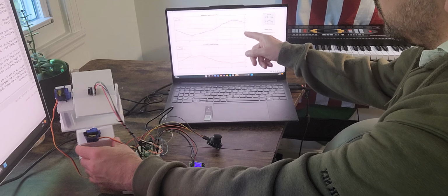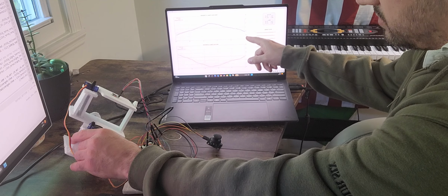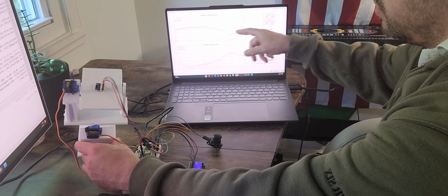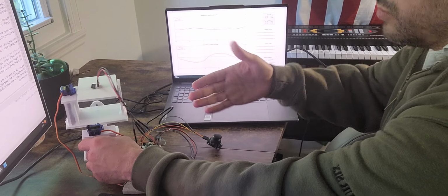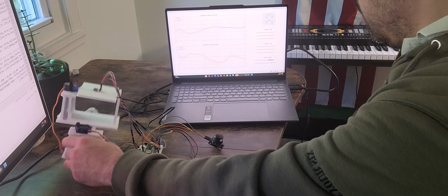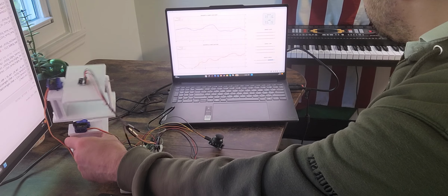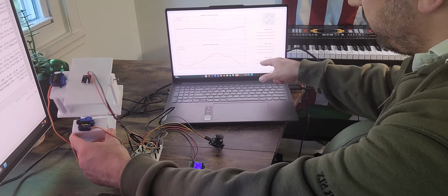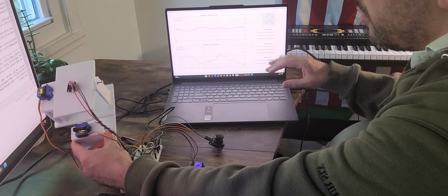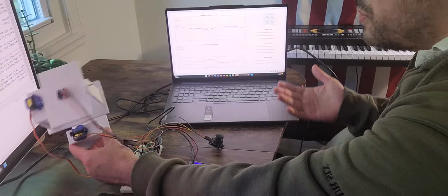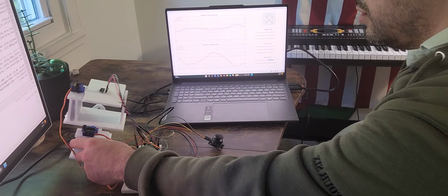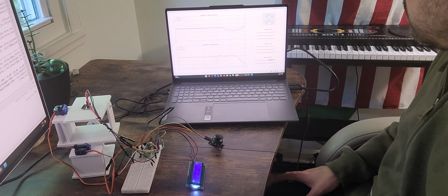On the graph, you can now see the full range of the motion without this trying to minimize it. And right now it is set at tau 0.525, which I think is about the optimum value for this tau coefficient of the complementary filter.